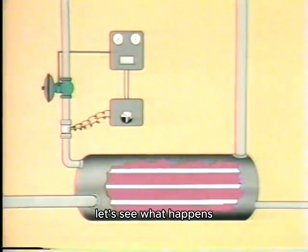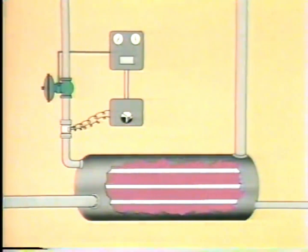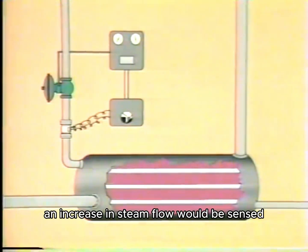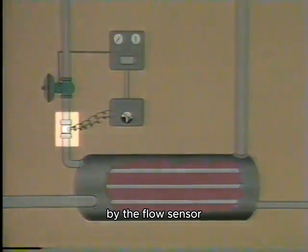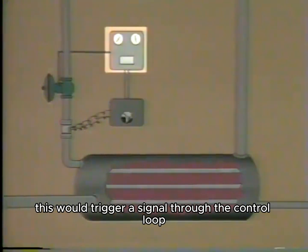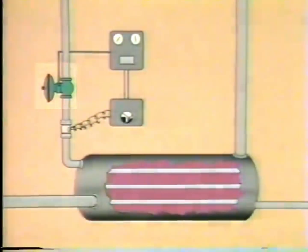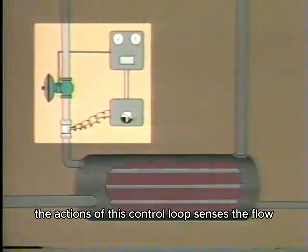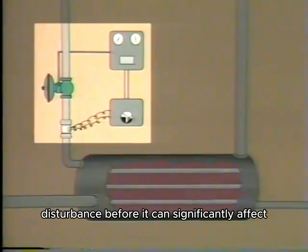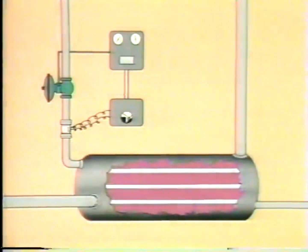Now, let's see what happens if we have a disturbance in the steam flow that causes the flow to increase. An increase in steam flow would be sensed by the flow sensor. This would trigger a signal through the control loop that causes the flow control valve to reduce the flow of steam. The actions of this control loop sense the flow disturbance before it can significantly affect the temperature of the water in the heat exchanger.